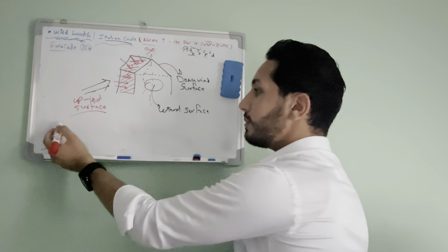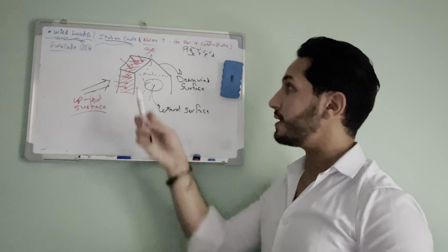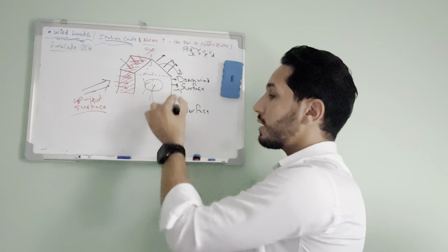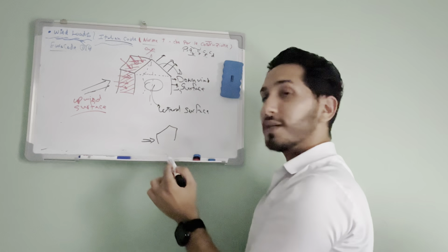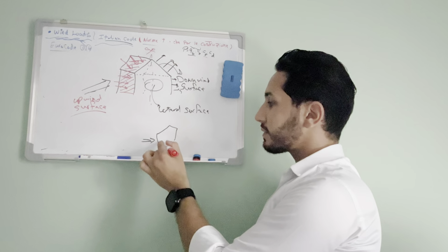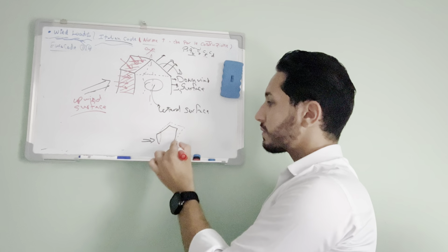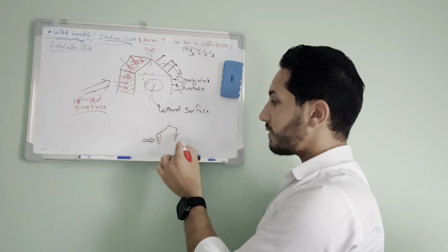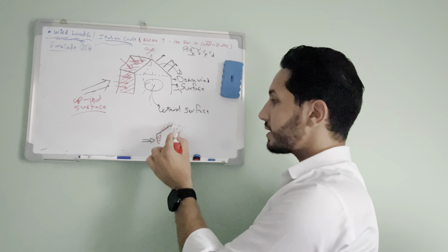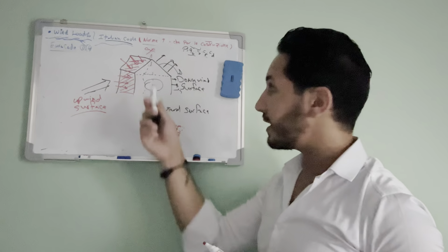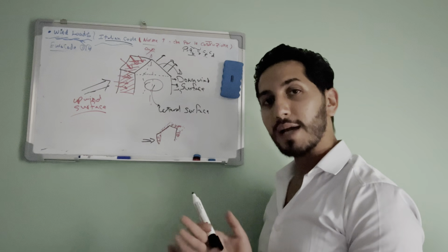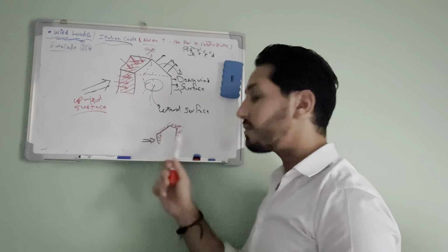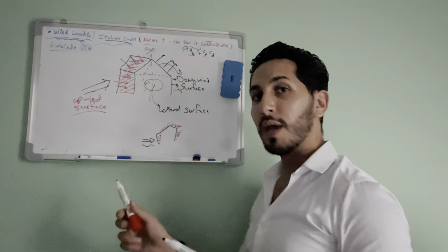What's gonna happen? The CB acts here by compression on these two sides, and on these other two sides we have tension. Why? Because in the 2D model, if the wind acts this way, the building is going to deform like this. So this side will have compression, this side will have tension, this side will have compression, this side will have tension. This is what happens when the wind acts from one side. Normally the wind doesn't come from one side, but we consider it as the maximum wind acting on the building from a specific side. We call this the main wind direction.